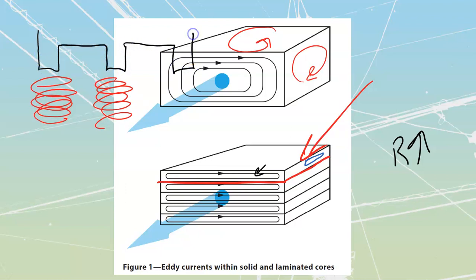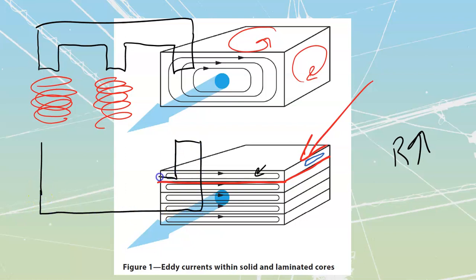and if it was a three-phase core, there'd be another one further down over here, and then they're going to have another set that is going to overlap and look the same on the opposite side. Let's draw this one out over here, and over here. So they make these windings just off of a plastic spool. They're going to bend them, insulate them, etc. And then all they do is take these two sets of laminations and press fit them together.